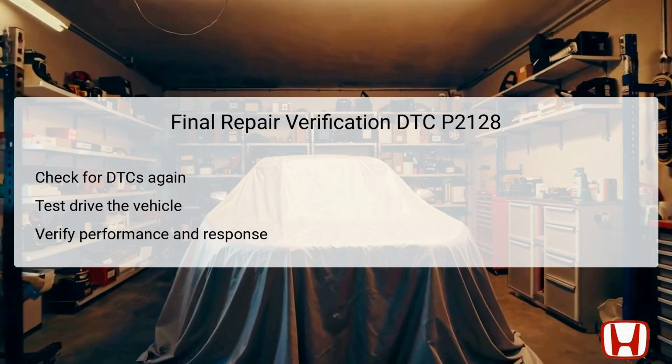After completing the required repairs for DTC P2128, it's essential to perform a final verification to ensure that the issue is resolved. First, clear any existing DTCs from the system and conduct a diagnostic scan to confirm that the P2128 code no longer appears. Following this, it is vital to take the vehicle on a test drive to evaluate its performance under normal driving conditions.